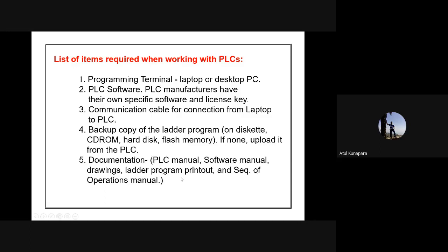And another thing is documentation. In documentation, you can have the proper logic diagram, or you can see your program instructions step by step, how you are working with it. And you need to have the PLC manual also, because it tells you the input and output pin number connections, how the input and output modules are going to be configured, and the software manual tells you how you are going to use your software. So all this is required.